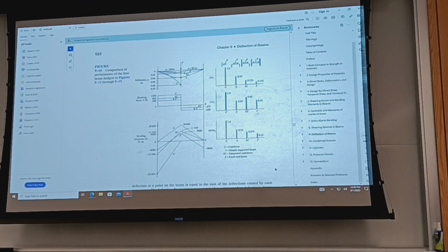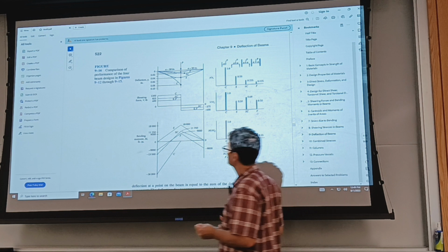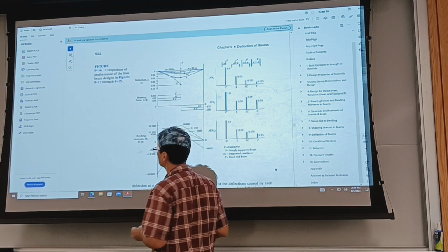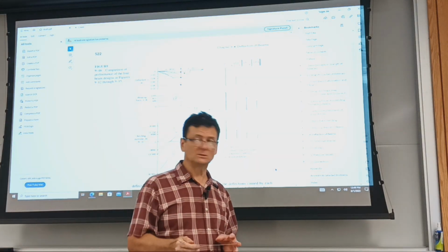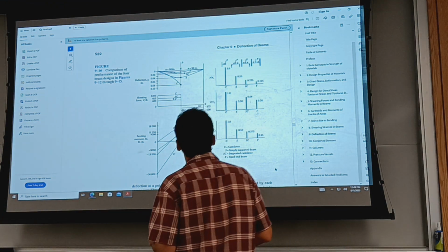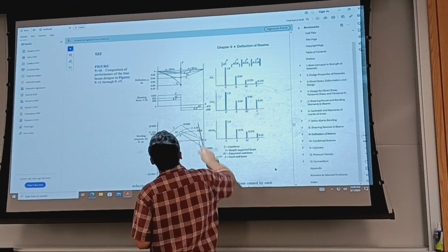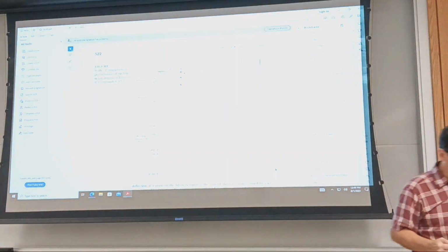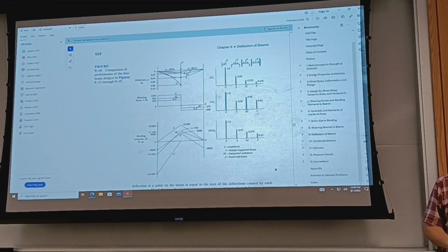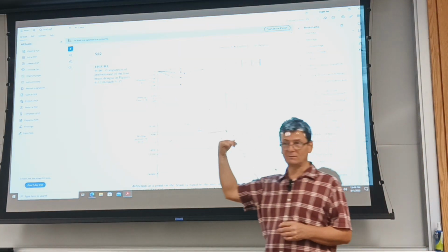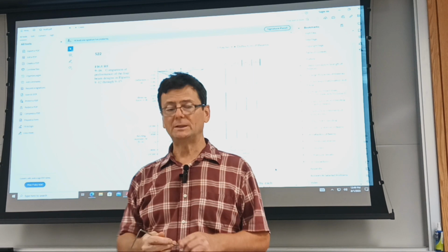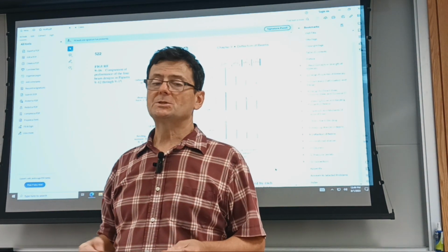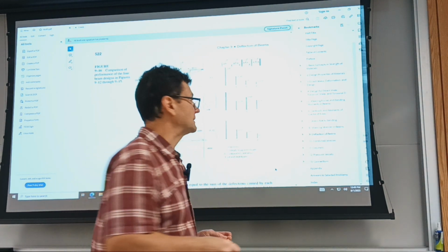There are ways of mitigating deflection other than changing the type of support. How can you limit deflection? Maybe by looking at the equations, and we can go back to the formula method in the appendix. You always see L going to power 3, and it's above, right? Or power 2 maybe, and other multipliers. So shorter beams will deflect less.